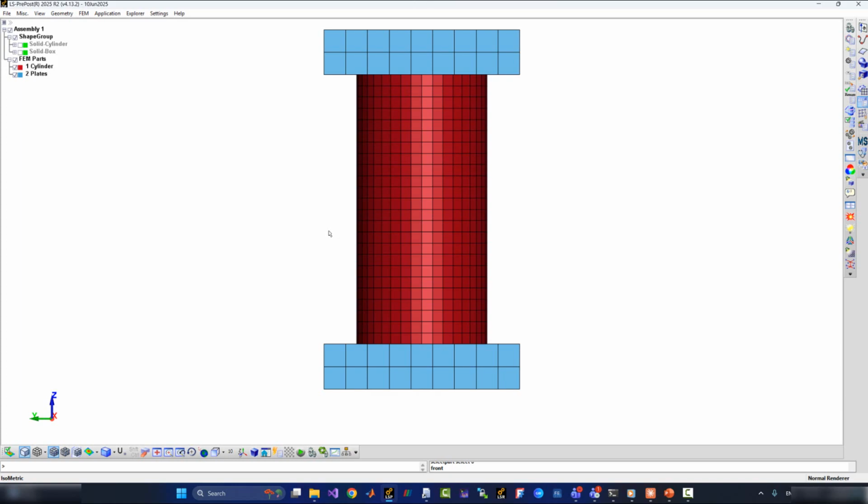What I'm going to create next is a set of 6 nodal sets. Okay, a set of sets, note this one. So I'm going to create a set of nodes, all the nodes that are at the bottom of the bottom plate. These are the nodes on which we will apply full fixity to denote the fully fixed support. Then we will have a set for the nodes at the top of the top plate, which are the nodes where we will apply this monotonically increasing downward displacement up to a value of 0.1 inch.